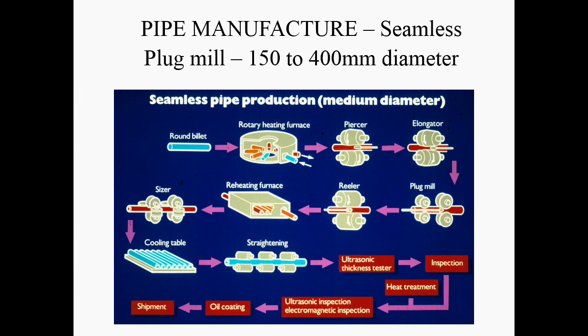By this time, because this material is quite hot, it's easy to plastically deform. The yield stress and the ultimate stress of materials drop as the temperature goes up. So you're trying to do this all in the plastic state. So these pipes probably have mechanical properties a bit similar to butter at these sorts of temperatures. Maybe a bit like butter that's come out of the fridge, but it's still pretty soft and easy to deform. And then when they're cooled, then you have the final good properties.